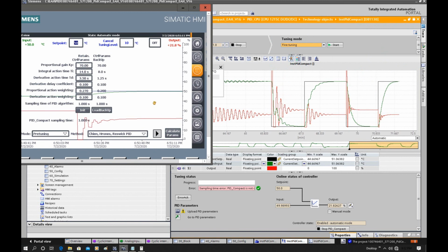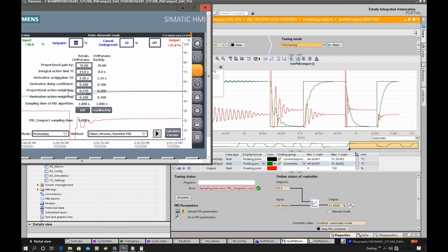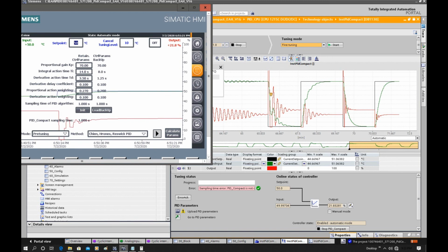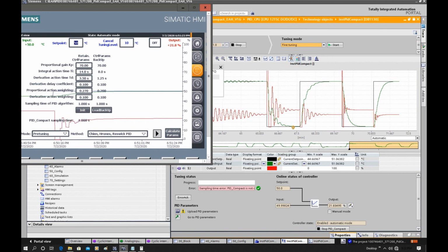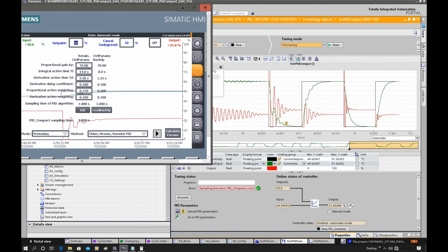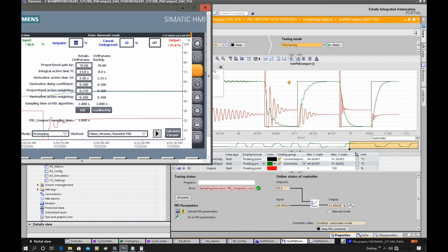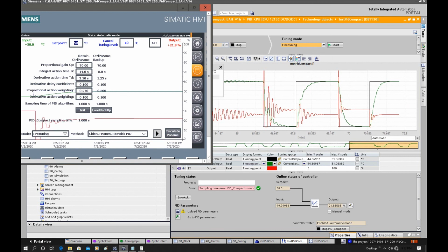Alright, that is for today. In this video, we changed the gain, integral, and derivative individually to check the behavior of the PID control and the process value behavior. And during the test, the system sometimes shows oscillation, sometimes it shows overshoot. Those behaviors are typical responses. Hopefully, those tuning directions could give you some idea when you do the fine tuning.